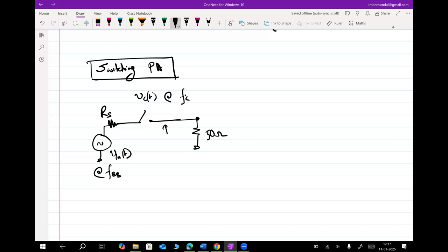So as it turns out, in these cases, if I use an amplifier also to raise the signal, the example that I was trying to give earlier, typical amplifiers are again common source amplifiers and some variants of that. The output impedances are never 50 ohm. They are much higher than 50 ohm. Right? You have done projects in the previous semesters, right?